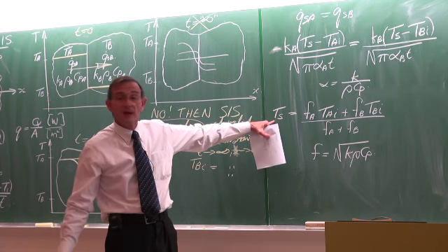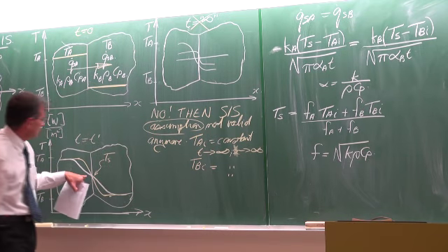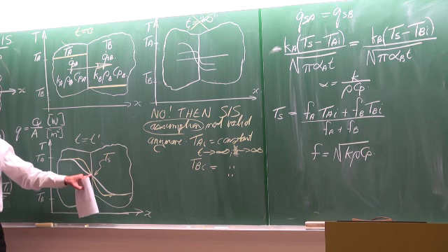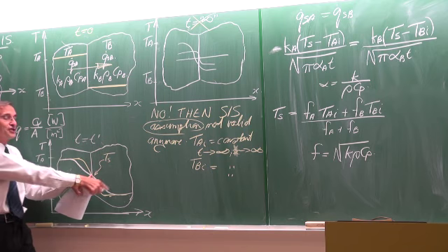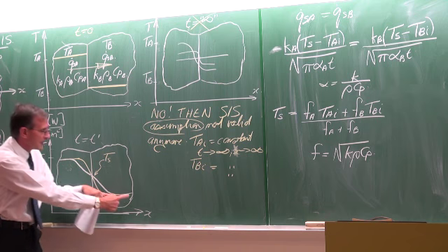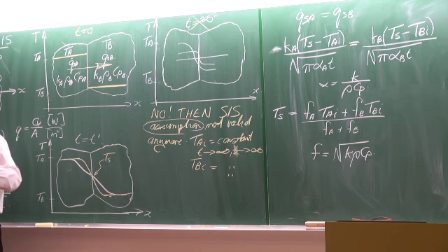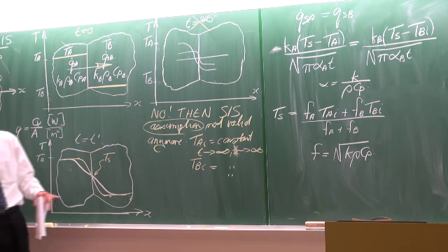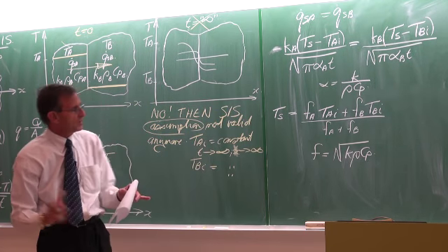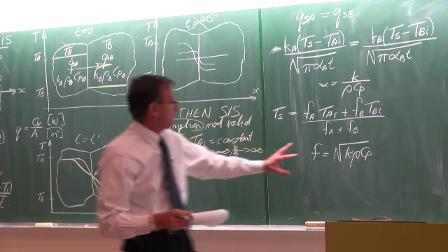So we see that the surface temperature, very important, that temperature there, is going to remain constant, obviously for as long as these two bodies are semi-infinite solids. So as long as this temperature inside the body and that temperature inside the body remain constant, that surface temperature is not going to change as a function of time. It's going to be a constant. Okay? And we can see it depends quite a lot on the different properties of the F values.